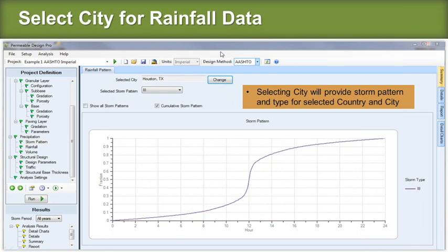What that indicates is that if you've got contributing drainage area, as Dave described before, not all that water is getting in there. So it's a safe approach for that particular number: if you just put 100 in there, you're in good shape. But if you actually know the initial infiltration rate of that permeable interlocking concrete pavement, fine, put it in there. It will definitely be over 100.